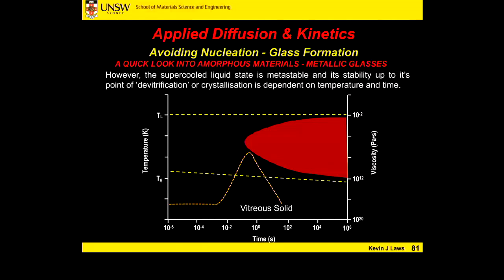We also know that with temperature increases, our viscosity decreases. All right? So it's always this trade-off. How far above TG do we go to reduce the viscosity? When we reduce the viscosity, the extent to which we can work the material increases. But we also then have to cool it much more quickly to avoid this nose. So there's a couple of different pathways that we can take. But all the time, we have to avoid crystallization in these vitreous materials.